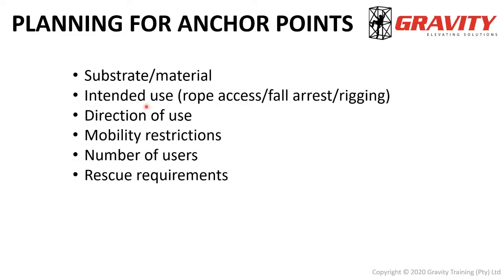Okay, so the intended use of the anchor point will determine the strength, the direction, the amount of anchors, all those kinds of things. So be very aware of what you want to use those anchors for. And again, make sure that that intended use is included in the installation process. So don't install a forest anchor point and then use it for rope access, for example.